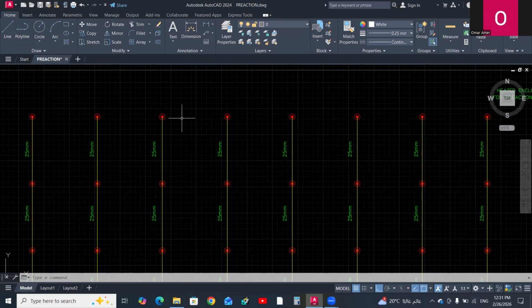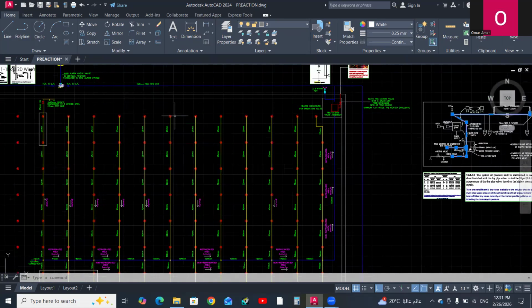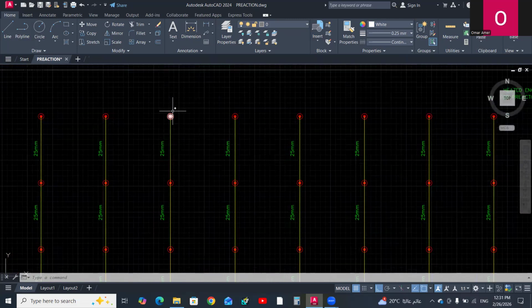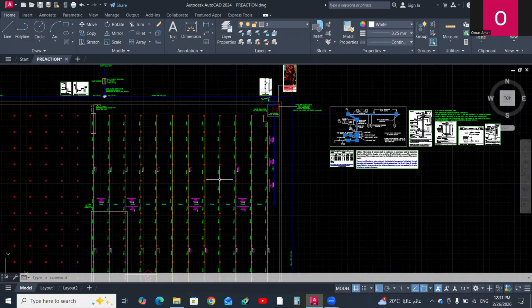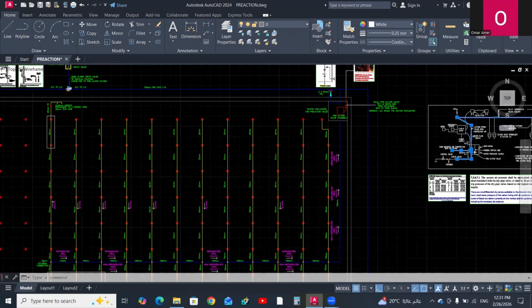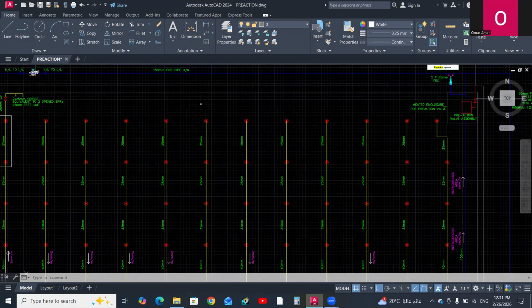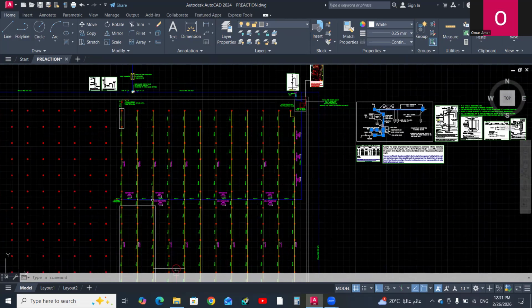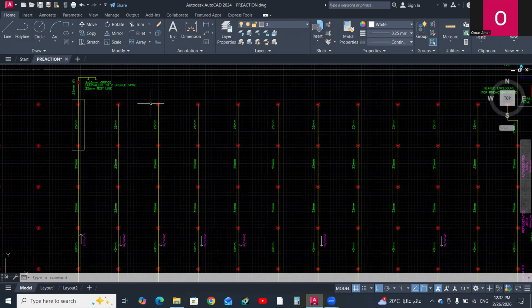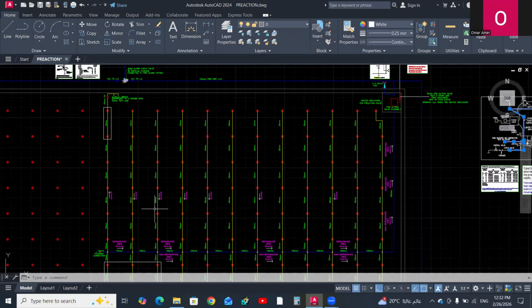This is not our topic now. You can check NFPA 13 requirements regarding sprinkler head requirements in storage areas, with the normal K factor, flow rate and density requirements. And the spacing requirements are usually similar to extra hazard: 3 meters maximum distance between branch lines, 3.7 meters, and between sprinklers on the same branch line also 3.7 meters.